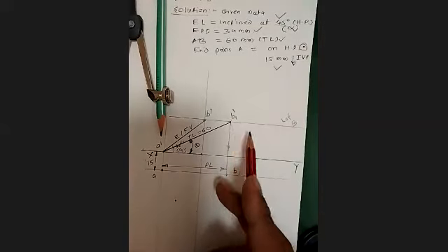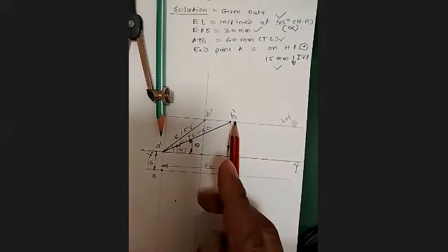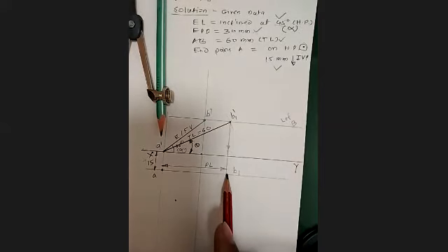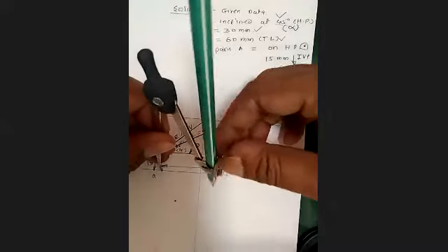I repeat. See, we have taken the projection from B1 dash till the locus of A, where I mark this point B1 because this is the B1 dash. So in top view, there is no dash, right? We'll denote front view only with the dash and top view without dash. So B1. Now this length A to B1 is nothing but your plan length. Now you can take this plan length because EL and PL we can rotate with the arc.